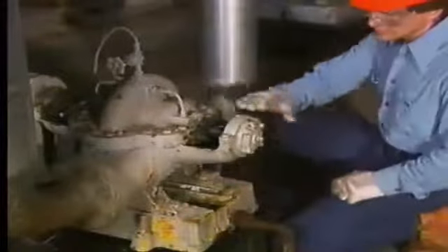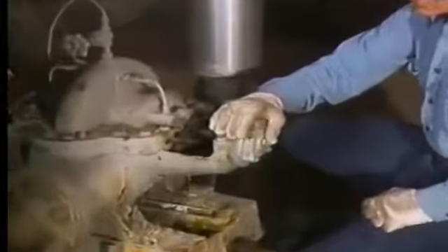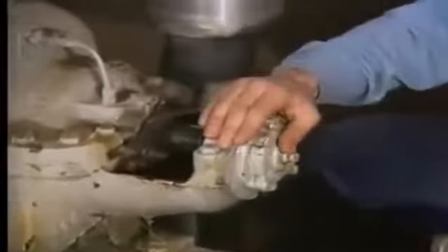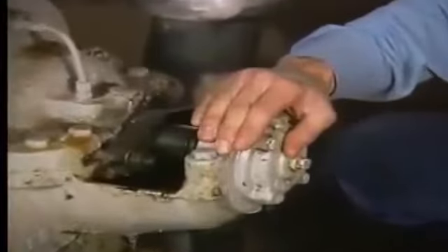After a bearing reaches its normal operating temperature, the temperature should stay relatively constant unless there is a change in operating conditions or the bearing malfunctions. Changes in bearing temperature can occur for a number of reasons. However, a sudden increase in the operating temperature of a bearing that cannot be explained could indicate a serious problem, including the possibility that the bearing has failed.